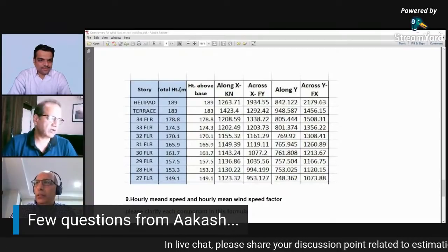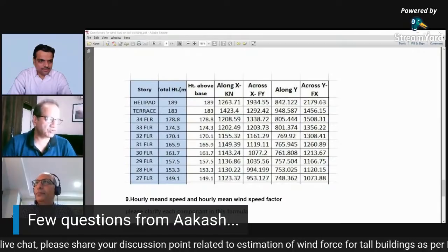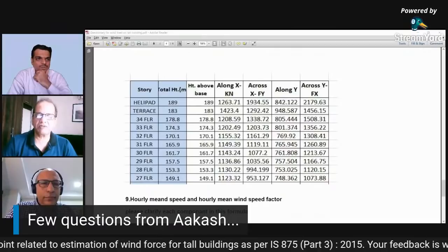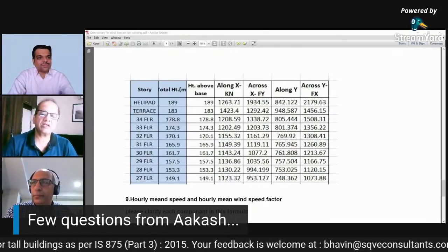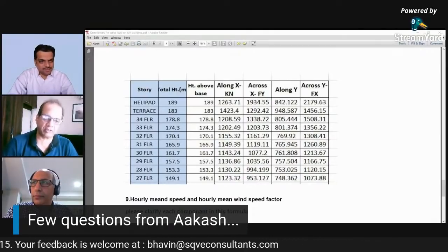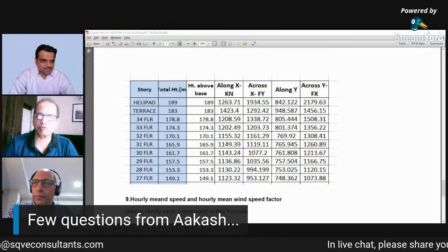Philosophically, a crosswind response, because there is no force, means no actual applied force in the crosswind direction. So force divided by stiffness and the response, that kind of formulation is not there. These are the actual measured forces in the crosswind direction, actual measured force spectra. And measured means they have been done on some specific buildings.